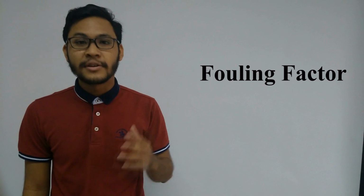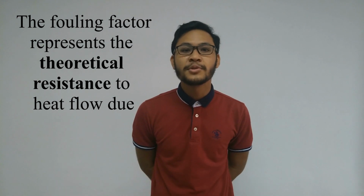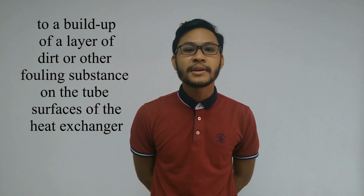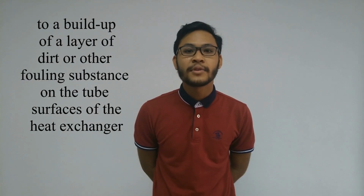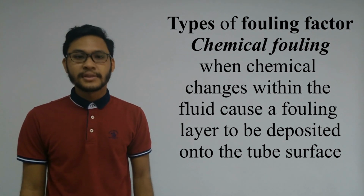For my part, I will be presenting about fouling factors. Fouling factor represents the theoretical resistance to heat flow due to the build-up of a layer of dirt or other fouling substance on tube surfaces of the heat exchanger. There are a few types of fouling factors. First fouling factor is chemical fouling.